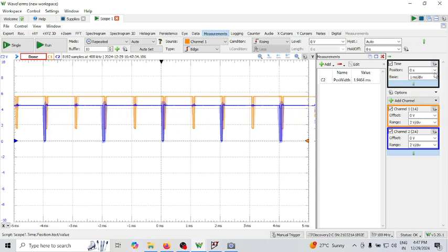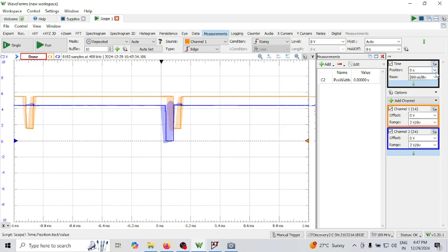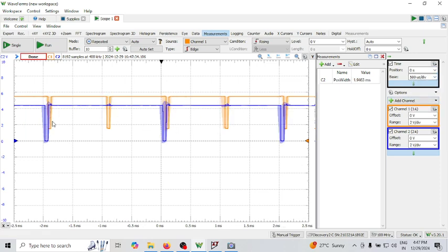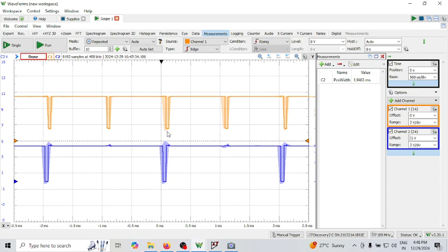See now, let me make it, that is too less. See now, here I have given a trigger signal. Can you see? Let me make an offset of around -5. See now, this is my first trigger signal. When I give the trigger signal here, for the first time, the output was in the stable state. It went to the quasi-stable state, and you can see it's remaining in the state of 1 because your capacitor is not yet charged.